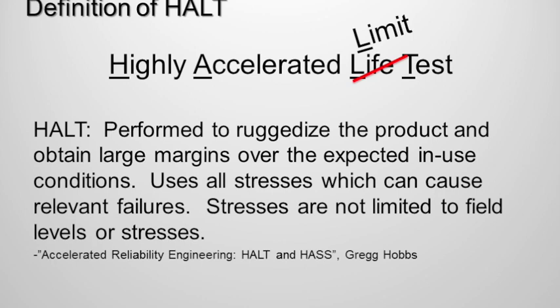And this idea of wanting to pass the test is a dramatic shift with HALT, because the idea is you want to fail the product in the test because you want to observe the failure modes, which means you're going to continually increment the stresses until you get failure responses so you can do root cause analysis.